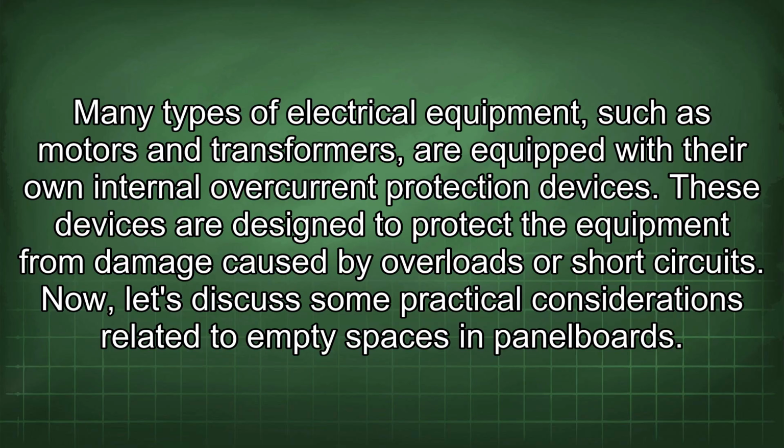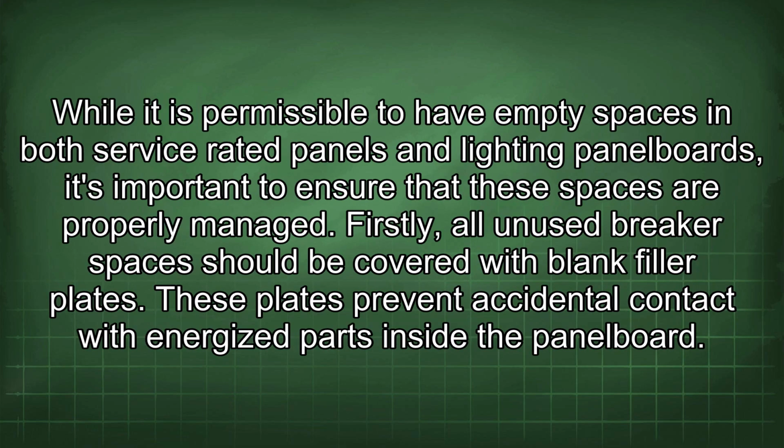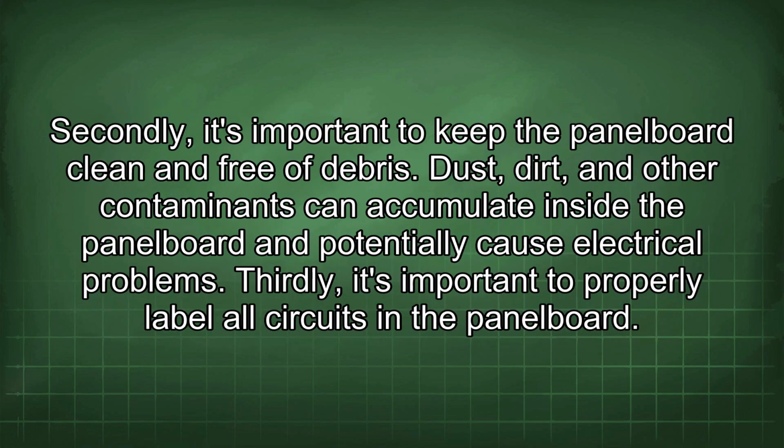Now let's discuss some practical considerations related to empty spaces in panel boards. While it is permissible to have empty spaces in both service-rated panels and lighting panel boards, it's important to ensure that these spaces are properly managed. Firstly, all unused breaker spaces should be covered with blank filler plates. These plates prevent accidental contact with energized parts inside the panel board. Secondly, it's important to keep the panel board clean and free of debris. Dust, dirt, and other contaminants can accumulate inside the panel board and potentially cause electrical problems.